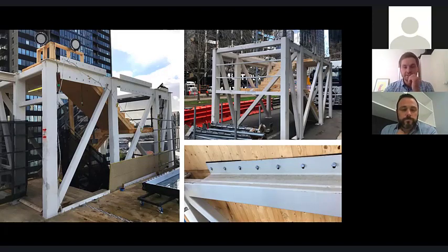Credit to the steel guys on this job, because I worked closely with them to literally drop the cages per 2 levels, as you can see here, by 2 millimeter increments up the building. So it was very precise for steel. I think they looked at it and thought that's a bit of a joke, but we monitored that all the way up the building to actually work in with the theoretical axial shortening. Yep.